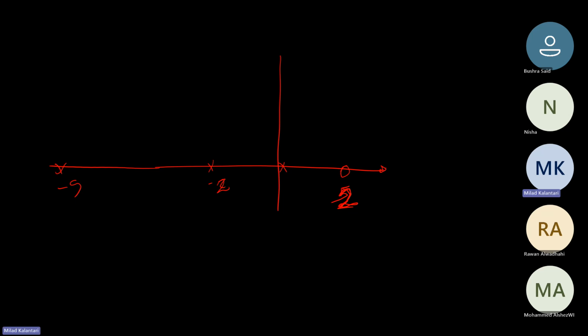Sorry, from -2 to -5. Is it the root locus or not? You mean from here to here? This region? Why? How many poles are at the right side? 3, right? It's correct. So then here is one location for the roots. How about from -2 to 0? Is there any root locus? Right? And how about from 0 to +2?